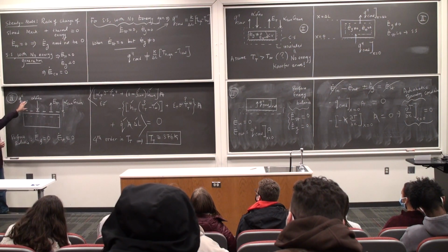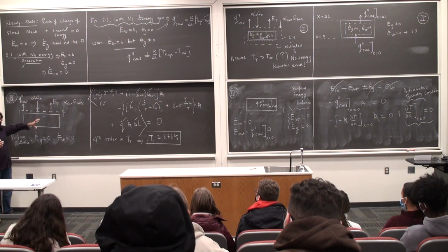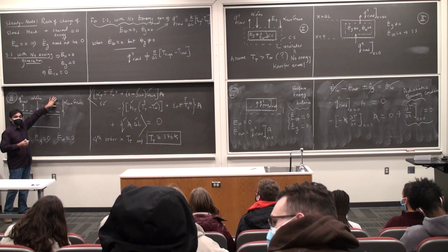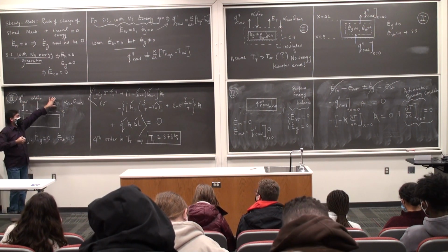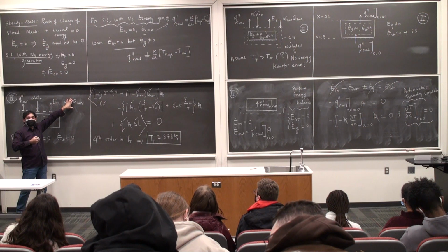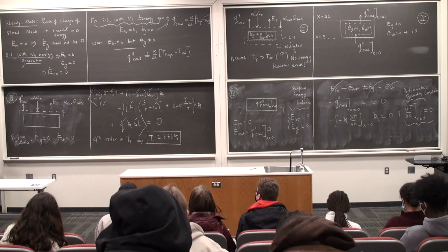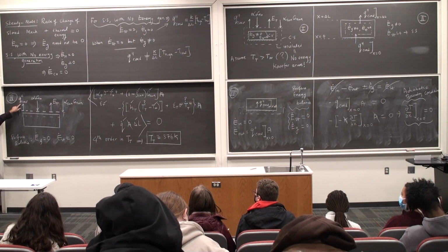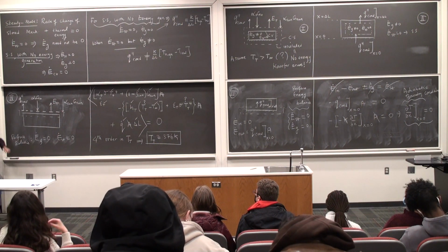Yeah. So, these are all absorbed quantities. They will always be coming towards the control surface as you're drawing them. This is an emitted quantity. This is always going out of the control surface. I don't mess with these arrows at all. Absolutely not. No matter what the temperatures are, you cannot do anything about these arrows. The only arrow that you have some sense of control over is this guy. And that too at the beginning of the problem, because I did not know what the temperature of the top surface was. But now I do know it, and so I have no control over that either.